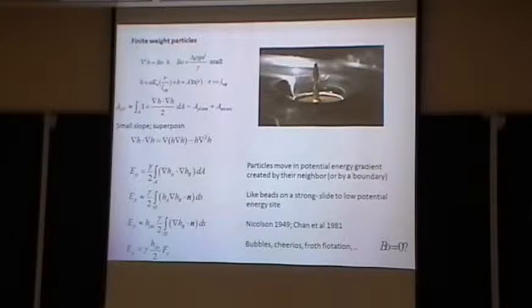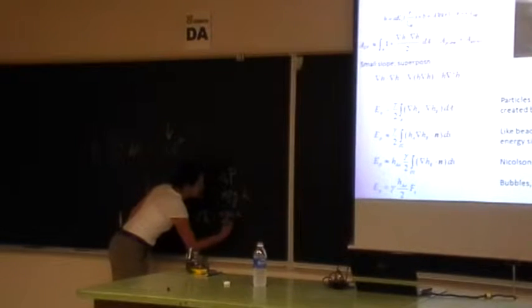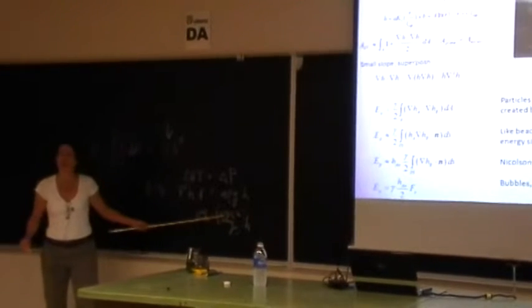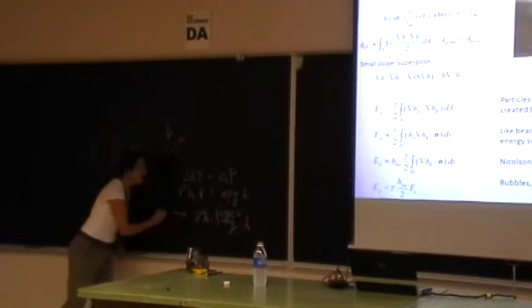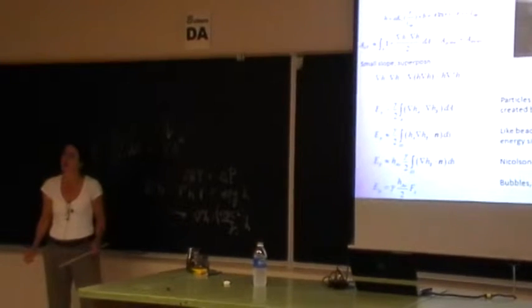If we normalize everything with, say, the particle dimension as the length scale, I can write this in a small slope limit, where the mean curvature is just a Laplacian. If I normalize everything, taking my characteristic length as the dimension of the particle, I'm going to get the Laplacian of h is equal to, remember my favorite dimensionless number? I don't know which one was my favorite last time, but I mentioned it. Some number, which is how important gravity is compared to surface tension, times h. So this is an equation that governs the shape of the fluid interface.